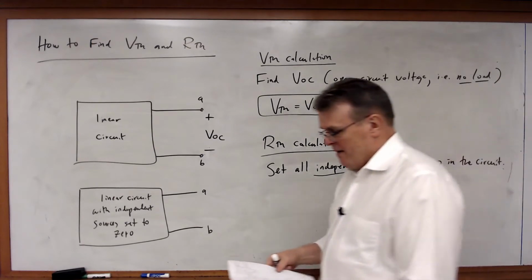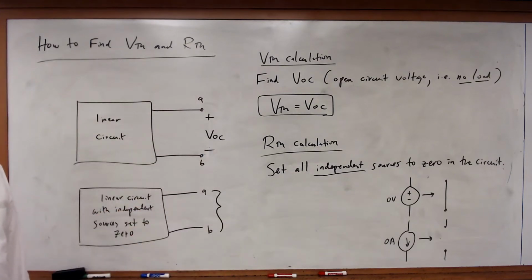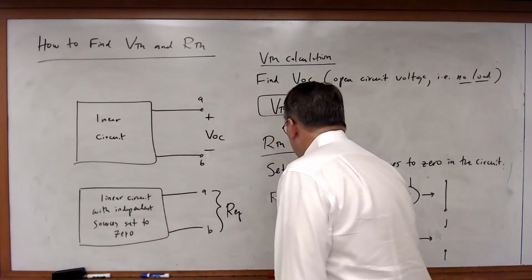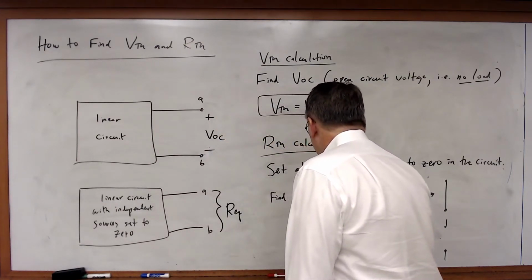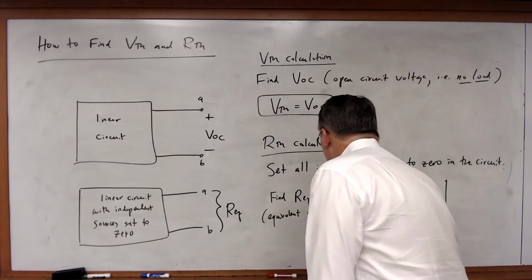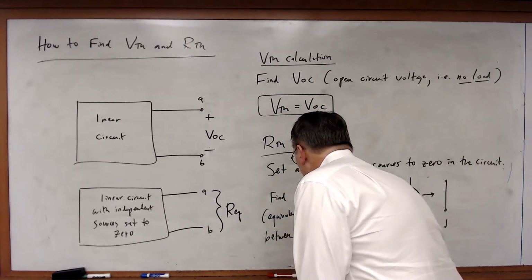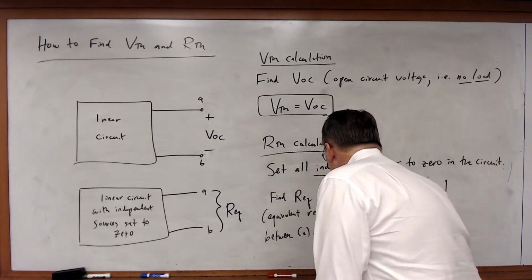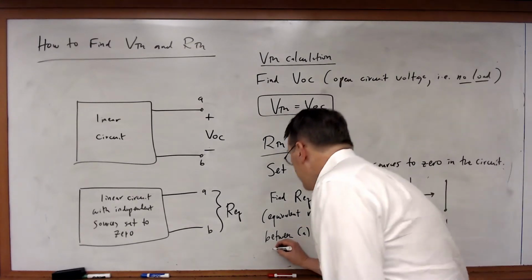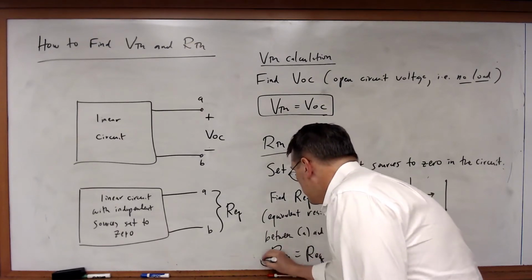Okay, once you do that, I calculate the equivalent resistance between A and B. And once you calculate that equivalent resistance, then Rth is just equal to that equivalent resistance.